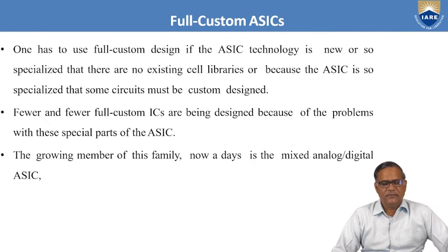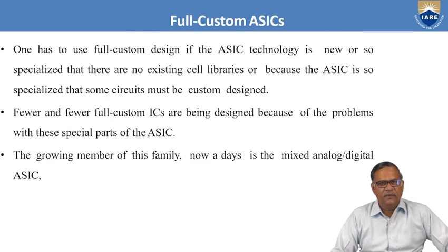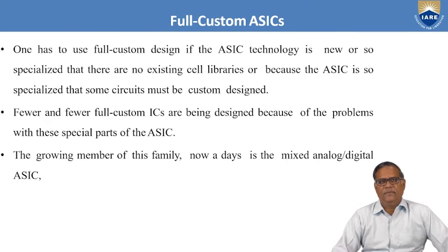One has to use full custom design if the technology is new or so specialized that there are no existing resources available. Because the ASIC is so specialized and innovative, the existing cell libraries or circuits are not suitable, so they must be specially designed.